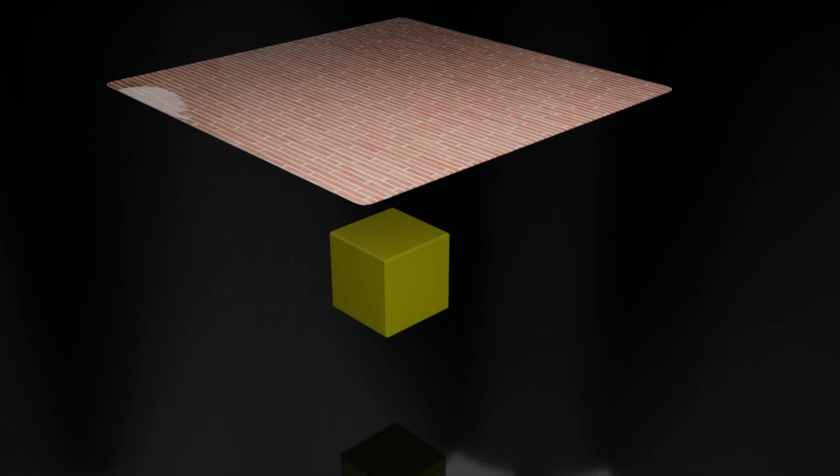If we just drop it onto a 3D object, what's going to happen is that the computer or the software does not know how to apply this. As you can see, the top one looks fine, but then on the side it gets all crooked and bent, as well as the orientation is different on the front as on the left and the right, just as we saw in the example before. So we need to support the computer or the software on how to orientate the 3D object, and how we can do it is through the use of UV unwrapping, and that means we have to open up or cut open the 3D object and lay it down as a 2D object.